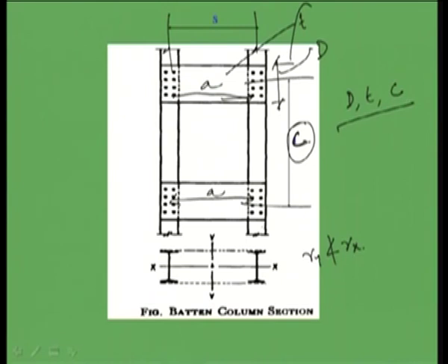That means we have the main plate of this and we have to attach this batten. So how many rivets will be required, what will be the configuration of the rivets, that we have to decide, or what will be the welding length, how much weld length is required. So that also we have to decide, weld thickness, throat thickness, those things we have to decide if we are going for a welded connection, right. So these are the things we have to decide.